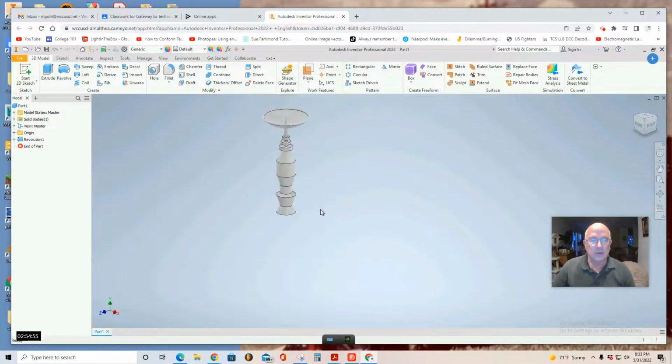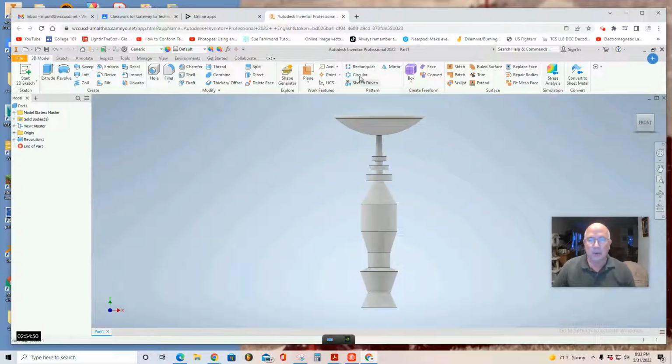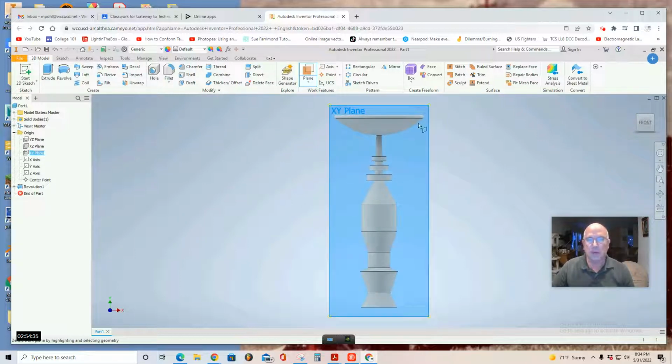And there's the beginning of my space probe. At this point, I'm going to create a plane right through the middle of my probe. So select plane. It just turns blue, nothing will happen. You have to move to the left to where this origin button is. Click the plus sign, find a plane that faces you, click, this is the XY plane,